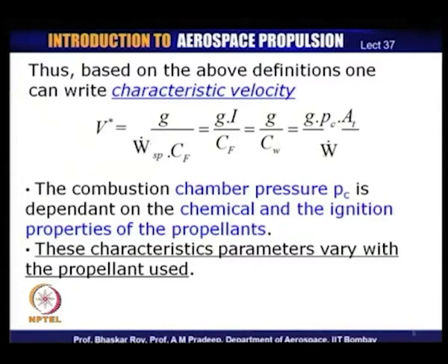So, it is to be calculated from the basic propellants that are being used, and hence it requires separate attention. However, as we see here, the combustion chamber pressure at any given point of operation is a fundamental parameter of importance. And hence, since they are dependent on the fundamental combustion chamber pressure, they depend on the propellant chemical properties, the basic propellant that is used, and hence the rocket engines are very strongly dependent on the basic propellants and their chemical properties.